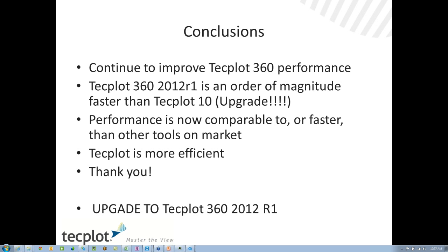Do I have to load the whole data set once or just one time step? That's a very good question. I believe this is in regards to the Fluent improvements. You're going to have to load the whole data set at some point to get the indexing file, because that's just part of the load strategy today. So today that's the way you're going to have to do it.